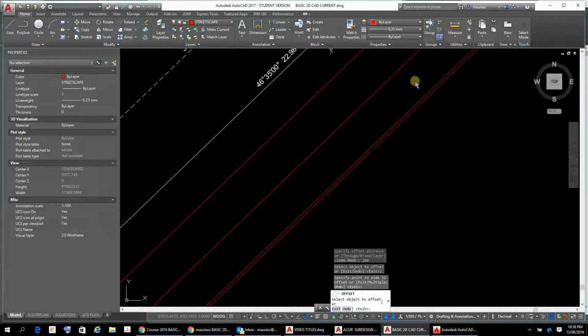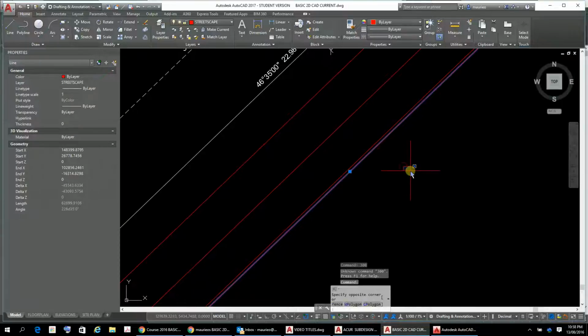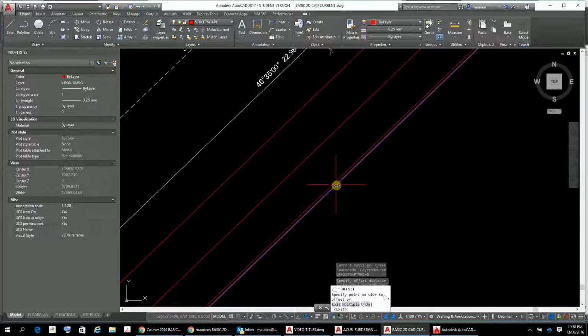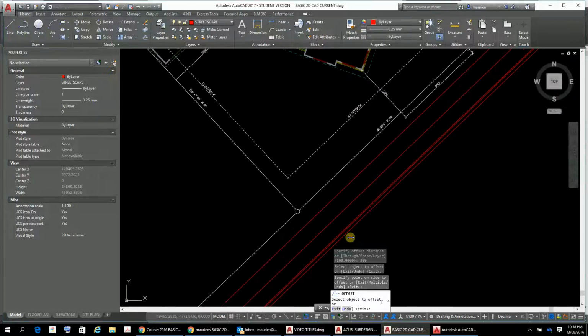And then we've got another one. If I go enter and select object or offset, I want to go 300, which is the, no, that didn't work. Okay, so offset, enter, 300, enter, and that gives me the lip of the channel, which is pretty much my street furniture how I want it.